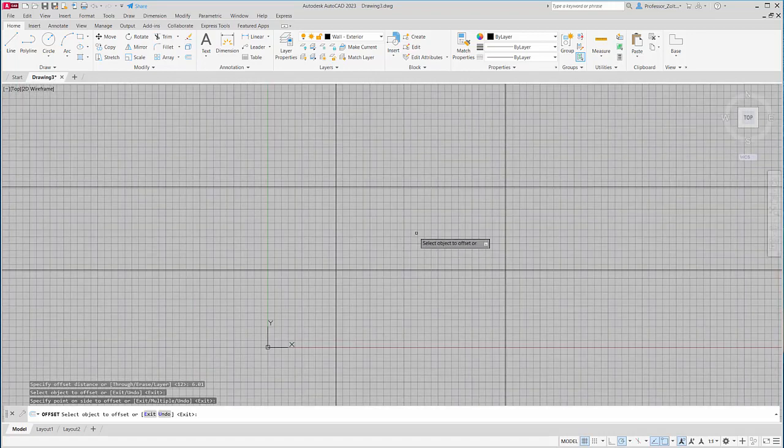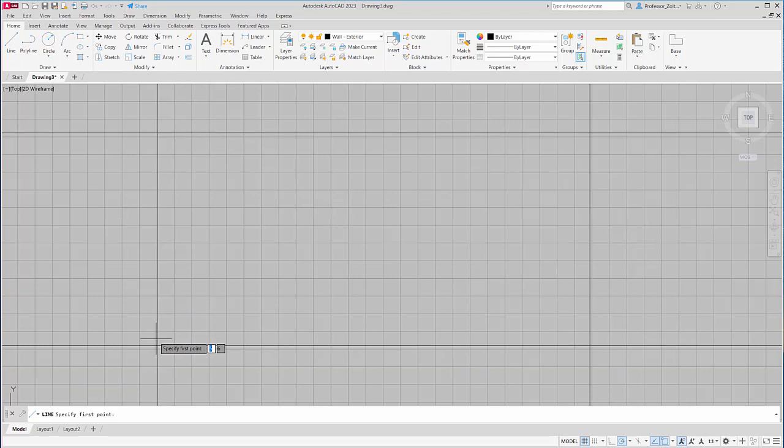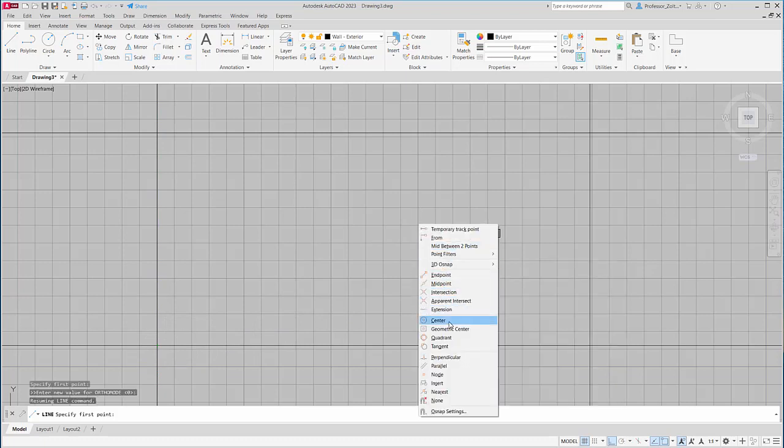So from here, I'm going to generate the outer edges of this, and if I want to, I can set a grid or anything to help me with my perspective of the drawing. I don't need anything else. So there's exterior walls. I have all these extra lines here, and I'm going to click on the line tool, and it's automatically set to find these intersections. So where do we set these values? If I hold down shift and right click, these are all the different points of geometry that we can find. These are called temporary overrides.